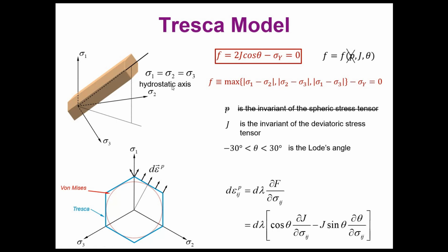It's looking for failure when you have distortions or when you have deviatoric stresses produced by the loads. And this is the reason why the equation again includes the second invariant of the deviatoric stress and the yield strength as well, that will be the plastic when you reach plastification.